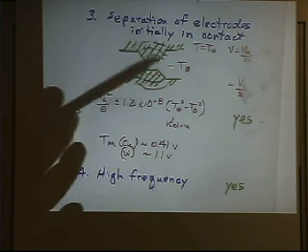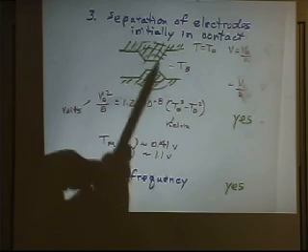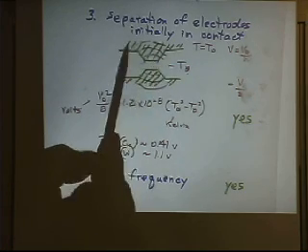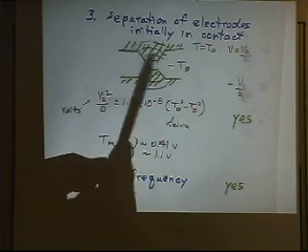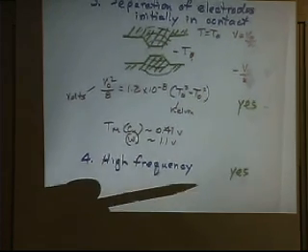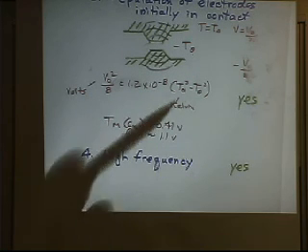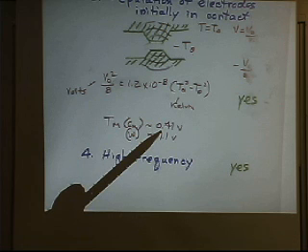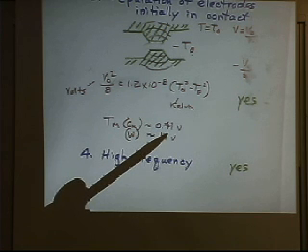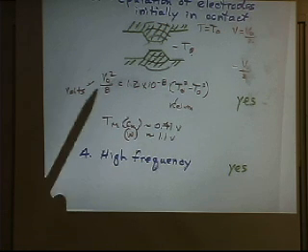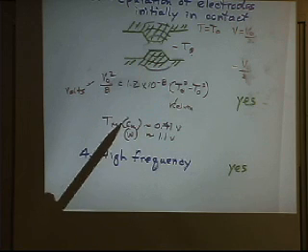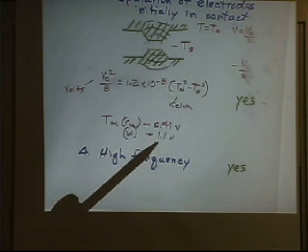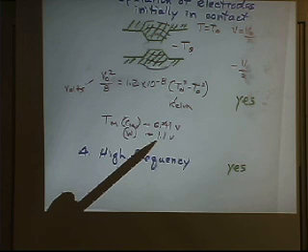It turns out you're solving Laplace's equation, and basically the voltage isopotentials in here look exactly like the temperature isotherms. It's just solving the potential equation in here. We won't solve it, but you end up with this equivalence between voltage and temperature. For different materials, like copper, the melting voltage is 0.41 volts. You now have this equation that relates temperature at the interface, and the melting point of copper is 1083 centigrade. The melting point of tungsten is 3300. It turns out the melting voltage of tungsten is only about 1.1 volts.